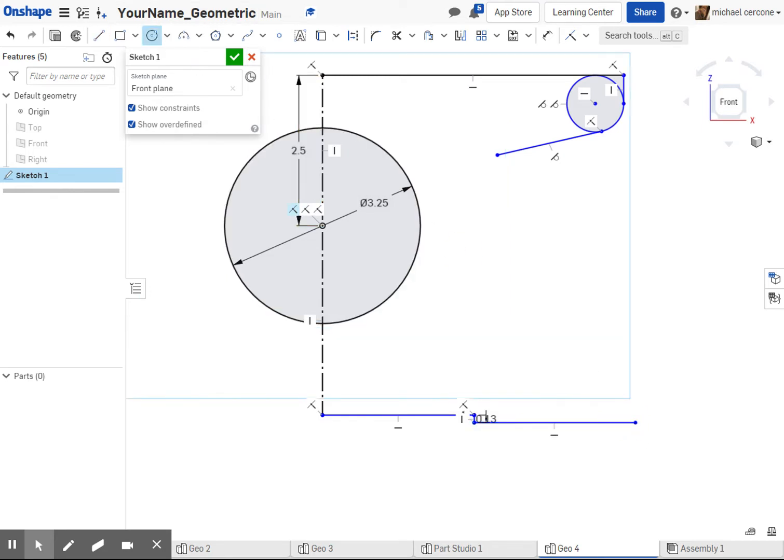So now I'm drawing a circle that's going to be vertical to this point, but also coincident to it and tangent. And just like I did before, where I needed a tangent line here, I'm going to just click somewhere, move my cursor over, look for coincident and tangent. And now there's a line free floating over here. These are connected by fillets. That's the only reason why I made this free floating.